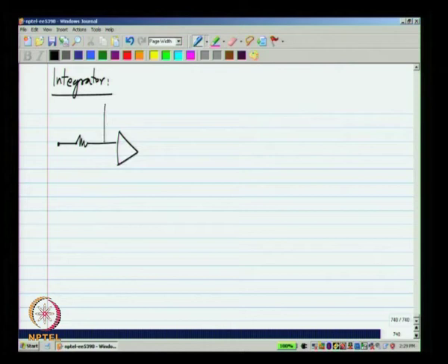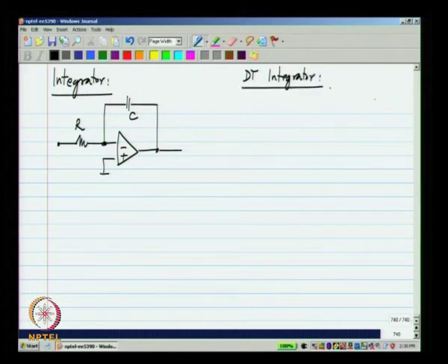I will show an op amp integrator here. Okay. Now, the discrete time integrator is built in a similar way to this. This capacitor you see holds the state variable corresponding to the state of the integrator. In the discrete time integrator as well, there is a capacitor C which holds the state of the accumulator. Okay. Now, what else do we need to have?